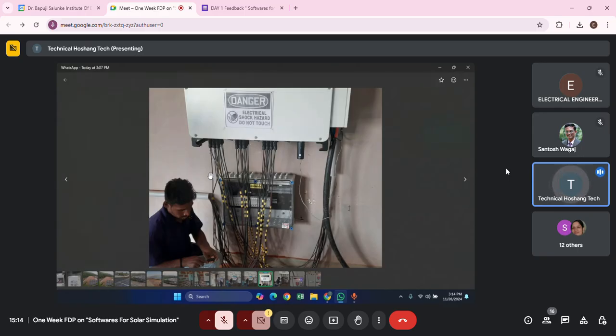If you speak about the wire, it will be almost 4 square mm solar DC wire. Specifically, I'm using this wire for such a reason that it is based on pure copper and it has less resistance. When a wire has more resistance and the voltage levels are high, there are chances of the wire getting heated up. For this reason, the wires connected with the solar panels are also DC solar wire, so that they do not heat up a lot.